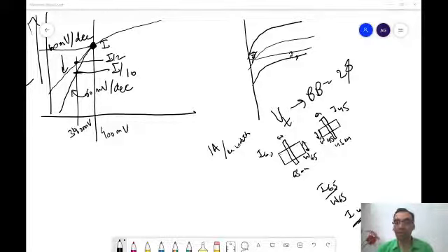There are extended source and drain regions, PMOS stressors, NMOS stressors, and many other things added in the technology so that VT comes back up or comes under control, whichever way. So many things are brought into the picture so that things are under control. Okay, but for our purpose, since it's a normalized value, we consider that. Yes. Okay. Meher?